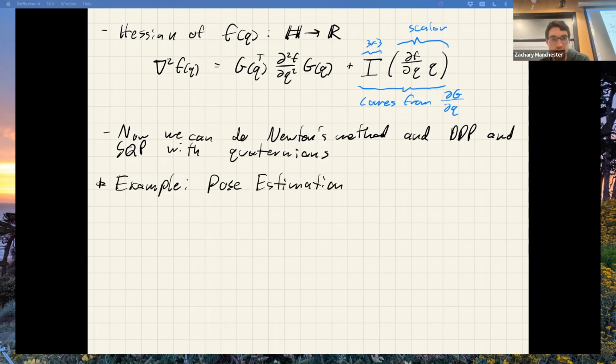So the idea here is if I have a bunch of vectors collected from a camera to like known features in the environment. So if I have like a map of the room and I have a bunch of features on the wall, say that I know, right? Whatever, like tags, something, fiducial markers, whatever. I know where they are in the world frame from a map. And then I observe them with my camera and I get unit vector directions to them in my body frame from the camera. That's the problem.